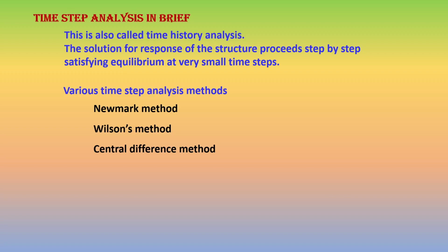With this knowledge, you interpolate to the next step and again set the equilibrium and the dynamic equations and get the solution for the structure for the next time step. So this way, step by step it will proceed, and there will be thousands of time steps in the solution.